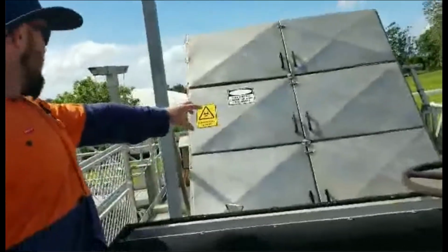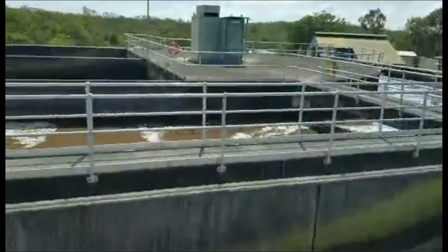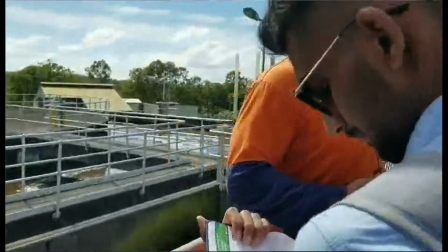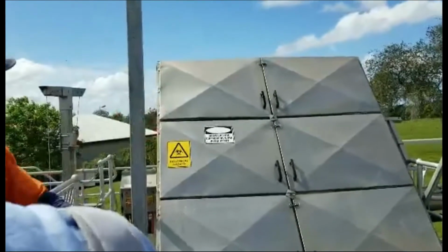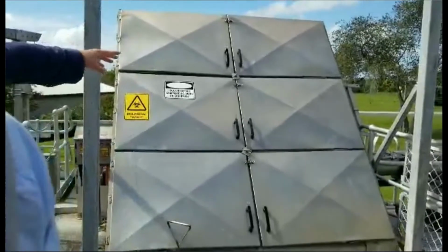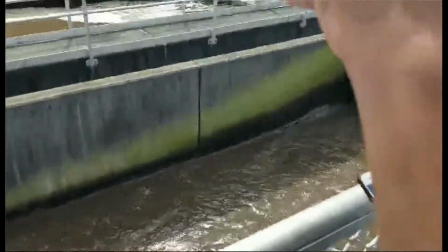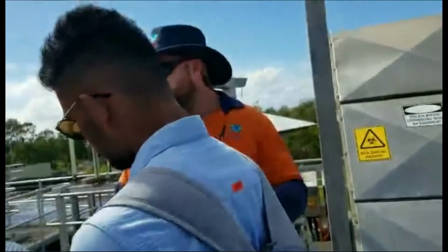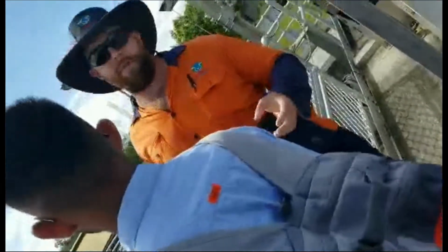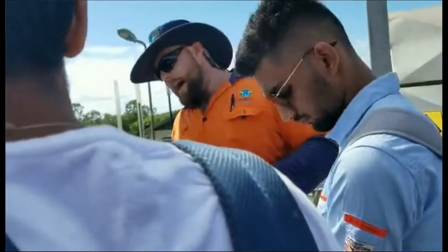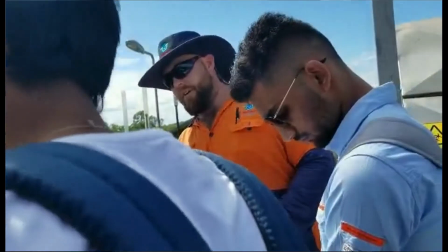After the previous step, the sediment and the solid waste in the wastewater have been removed and the water flows into the bioreactor. The purpose of this part is to convert the organic pollutants in the wastewater into stable and harmless substances by using the oxidation of microorganisms. The purification method is the biological contact oxidation method, a cross between the activated sludge process and biological filter membrane technology. Its characteristic is that packing is installed and bottom aeration oxygenates the sewage, and the water is kept in a state of flow to ensure good contact with the wastewater in the packing.